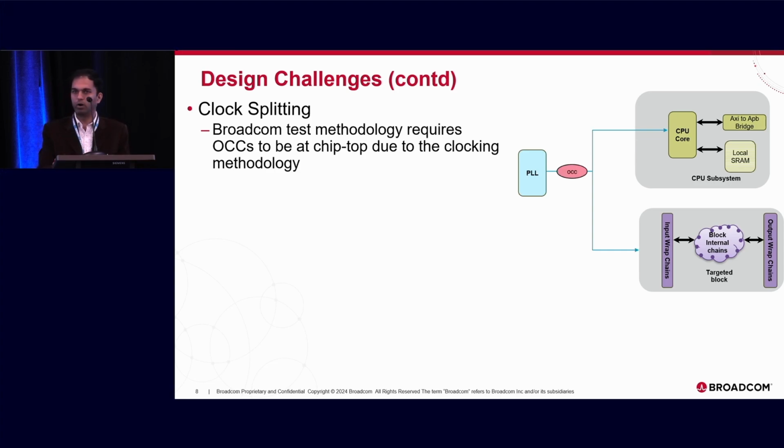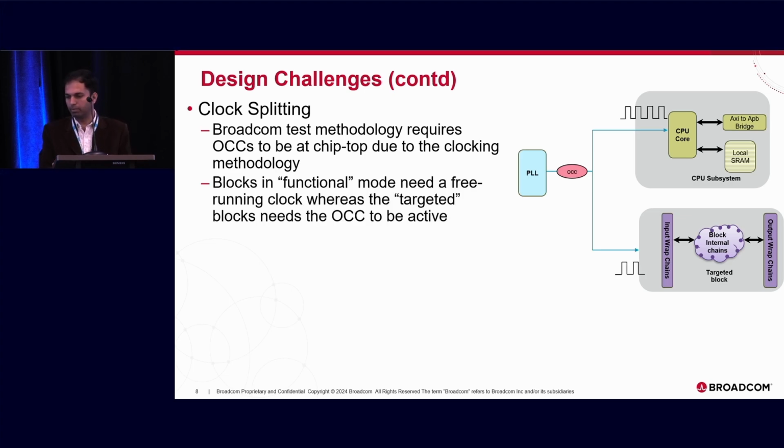functional block. So for normal EDT patterns, we'll have a common OCC, which can drive both of them. But here the problem is when we are in IS-EDT mode, the functional block needs a free running clock, but the targeted blocks need the OCC to be active. Now this is a problem, right? So we thought of a couple of solutions.